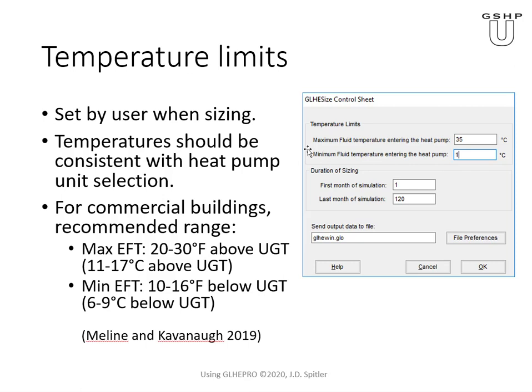Okay, when you actually go to size a ground heat exchanger, you'll choose the configuration. For example, a 10 by 10 field of boreholes with 100 boreholes. You will specify everything about it except the depth, and then you'll use the sizing function to find the depth. And if you find it's too deep or maybe too shallow and you'd like to go deeper, then you can choose a different configuration.